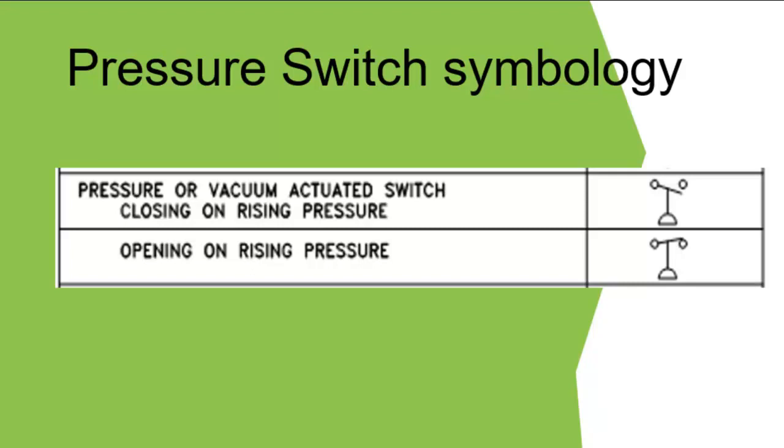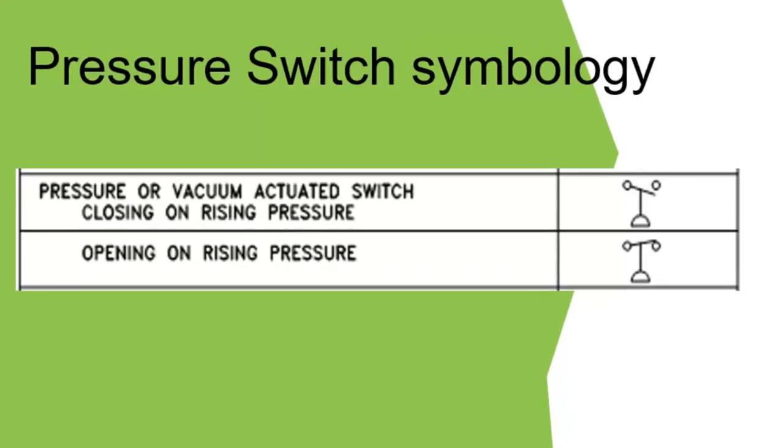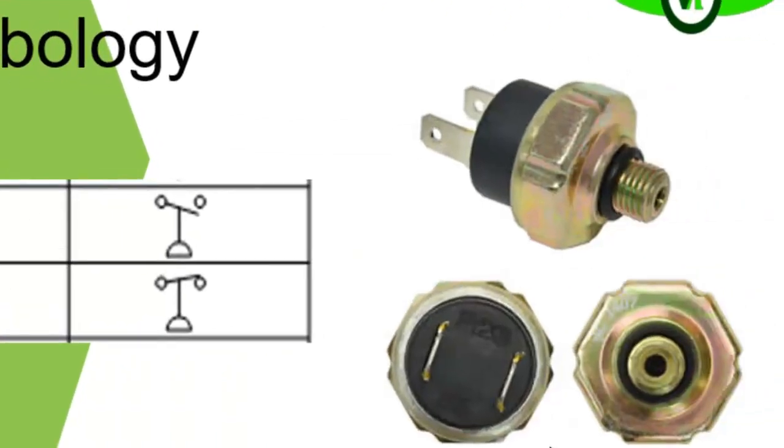So here is one. At one end you see the orifice to which the impulse line from your process is attached. The pressure in your process is sensed at that orifice. There is something like either a strain gauge or a diaphragm that helps to sense the pressure. As the pressure sensing device moves, you will see that it can either make or break a contact within that switch.